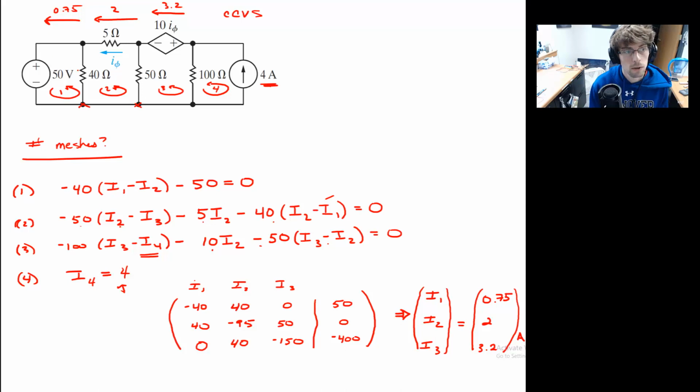All right. Well, okay, so if we take the difference between I2 and I1, that's the current flowing through that 40 ohm resistor. We'll say I2 minus I1. Well, that is 2 minus 3/4, so that's 1.25. And notice I've written I2 as the first current. That means that I am going in the same direction as I2, which would be down.